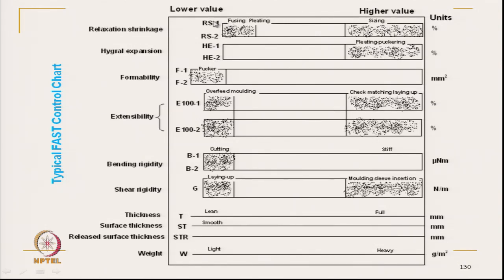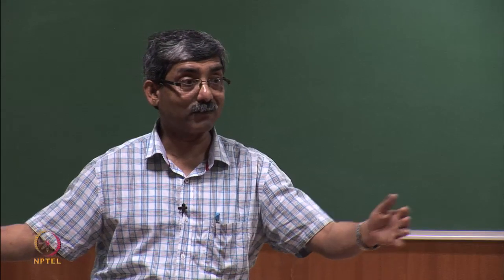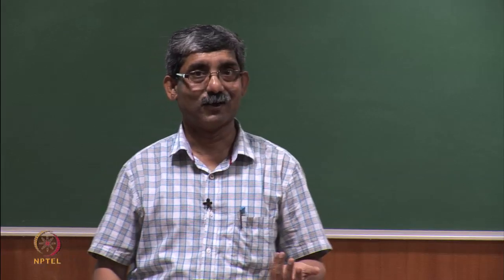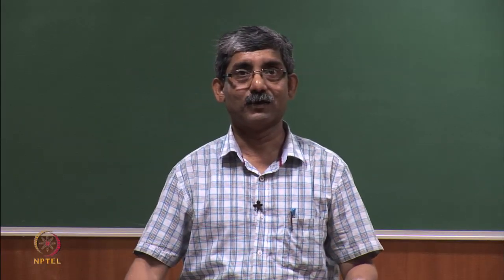See, RS1 relaxation shrinkage, if it is very low, what will happen? The problem may be a fusing or pleating problem. So, that problem it may create. If it is high, that is a sizing problem. If the relaxation shrinkage is high, that means the size may get changed. So, that type of problem will be there.